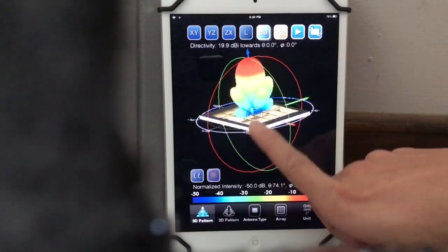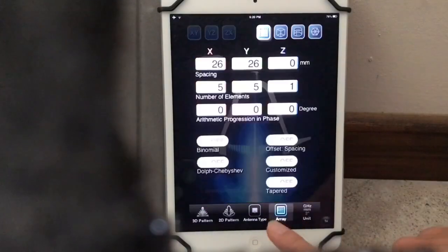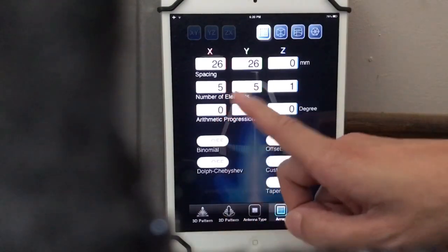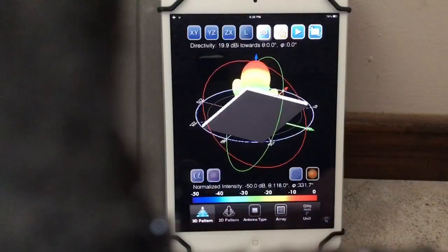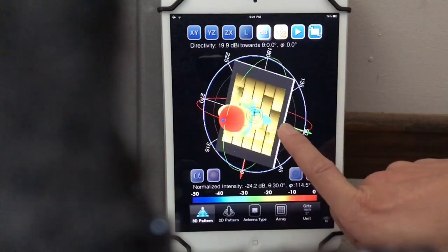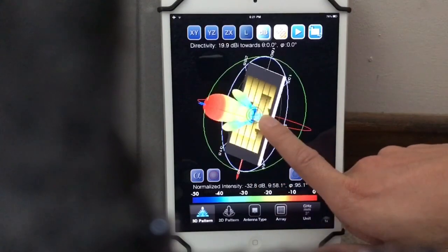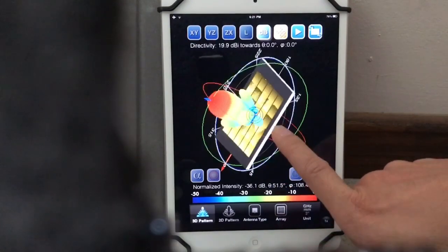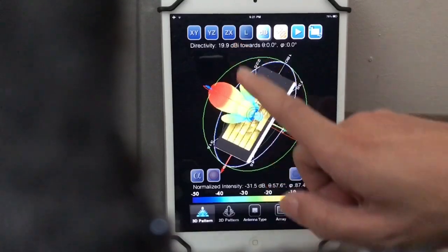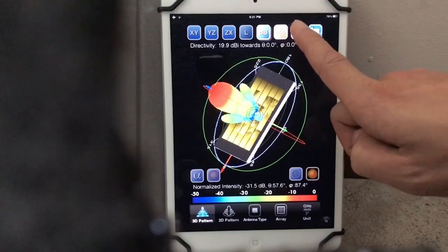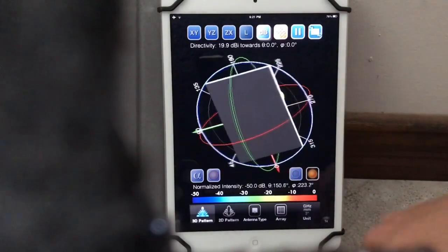This is the one that I pick, which is this 5 by 5, 5 antennas. And there's a play button here basically. Oh, look at this, this is crazy. This is like 5 by 5, this is like 25 patches, and the gain is close to 20 dB as you can see here. You can hit on play and it will rotate.